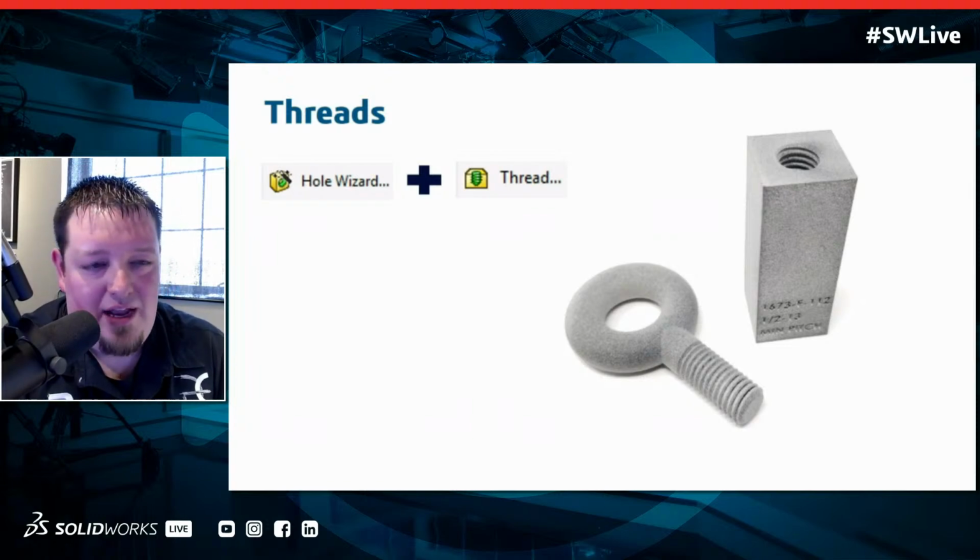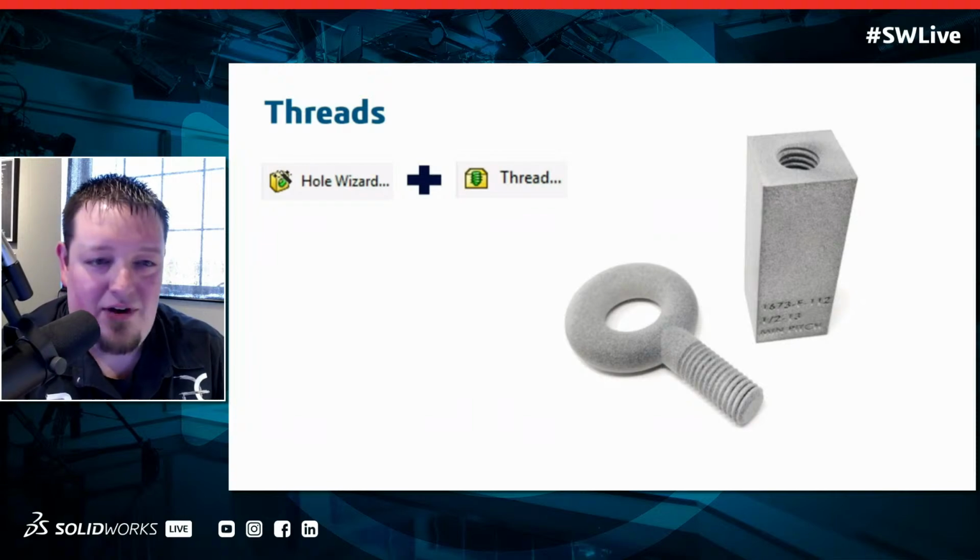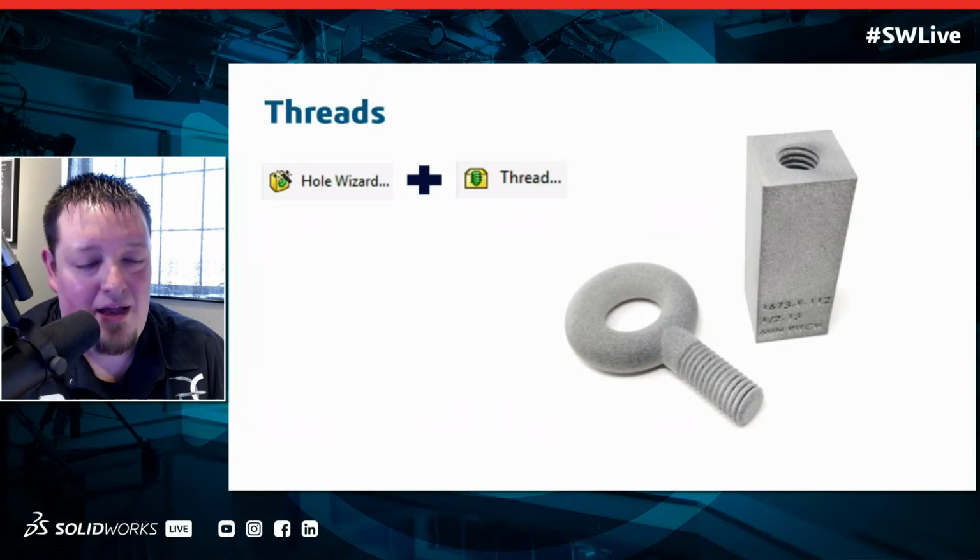The thread tool is really handy. You will get a warning message the first time you use it that says this is going to essentially destroy your performance if you use it. Ignore that warning, but I will say this is the last thing you want to do on your model. You want to get everything else done, and at the very bottom of your tree, you want to put these in, because you will take a performance hit. So you want to put it in a place that's easy to roll back and suppress if you have to make engineering changes.